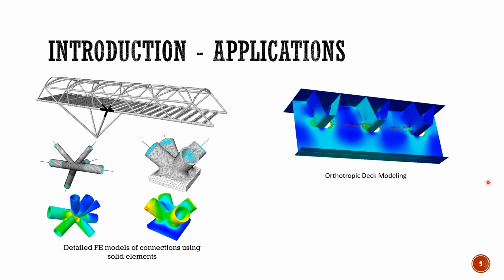The global model created in Civil will allow us to design individual members, but the local stresses generated at the joints cannot be determined from the Civil model. Hence, it is necessary to design the joint using finite element modeling that will help in determining the local stresses at the joint location, so that steps can be taken to ensure stresses are within permissible limits. The joint is modeled using FEA NX in this particular case.